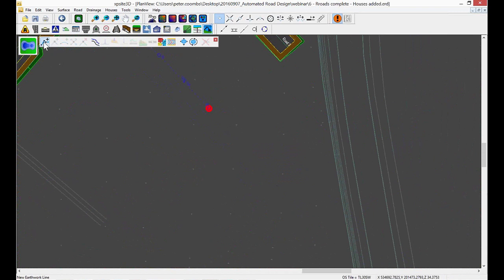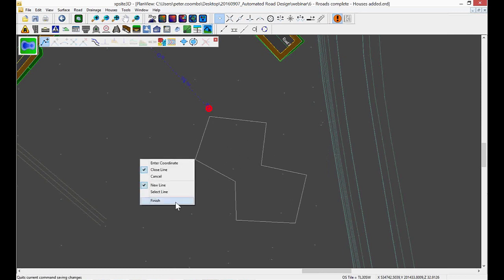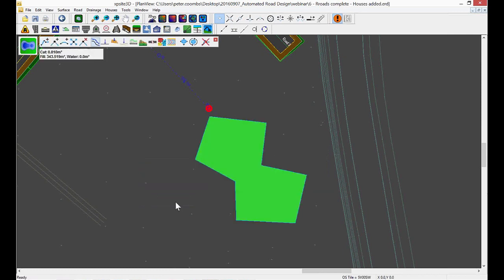And again, we have our similar kind of familiar toolbar that pops up, so I can create a new earthwork line. And from here, where the pipe is going to sort of discharge into the pond, I could just define something. This is really showing you why I came from a civil engineering background and not from a landscape architect background, because we don't typically make ponds that way in such shapes.